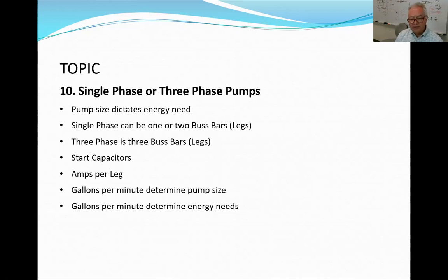Since we're using solar, we're only going to have 5 hours a day where our pump will be working. So we have to design a pump that's going to get us all of the water we need in 5 hours. We can have maybe a backup pump or something like that. This is another reason for the storage, not energy storage, but water storage. Once that water storage, the cistern, is full, you always have a reservoir of water sitting there in case you have low sunlight during the day. You can always go back to your storage and have that for your backup water needs.